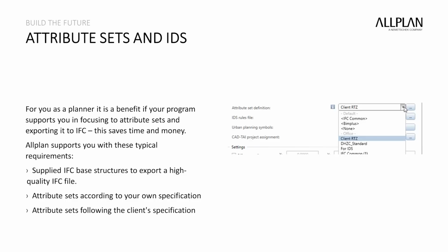First, supply IFC-based structures to export a high-quality standard IFC file. This is the standard use case. Second, attribute sets according to your own structure. With the years you will adapt it more and more. And third, attribute sets according to the client specifications, especially for larger customers.